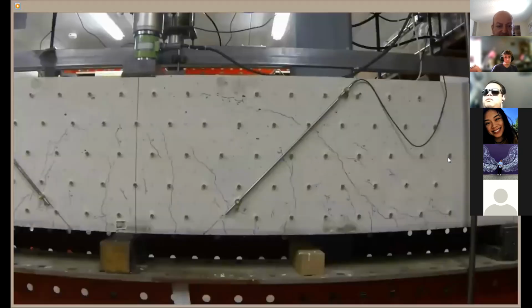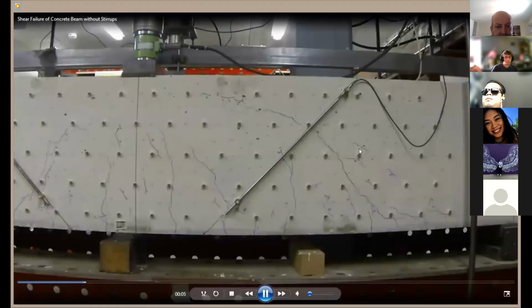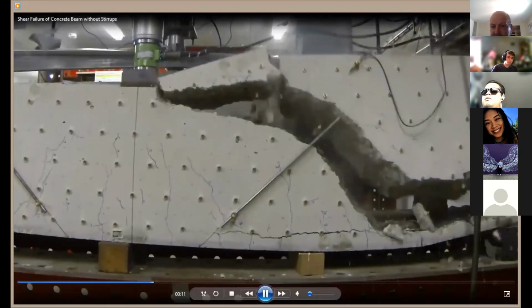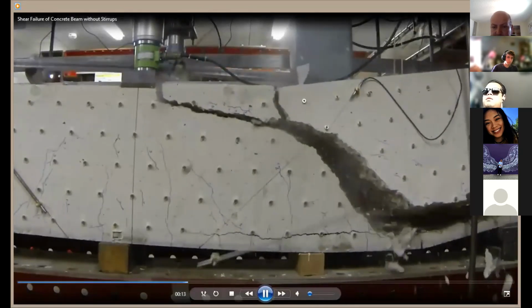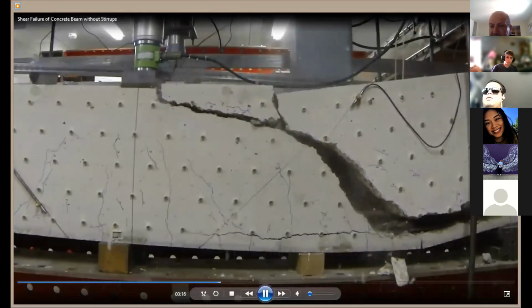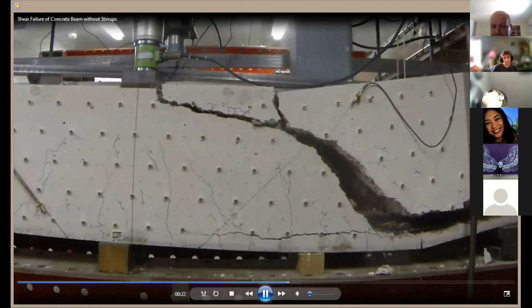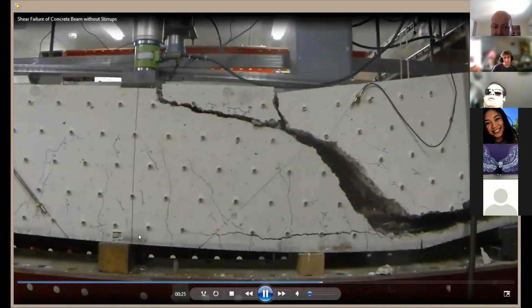So, okay. How about in shear? What's going to happen? Let's look at the shear test. Here's the beam, you have 1-point load, and look how it fails. Now, my understanding is the crack direction is going to be perpendicular to the force direction. Meaning, when you have a vertical crack, you're going to have horizontal force for the tension force. When you have a crack on an angle, I'm expecting the force to be perpendicular to it, which means the force is going to be in a diagonal direction.